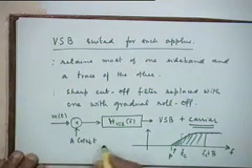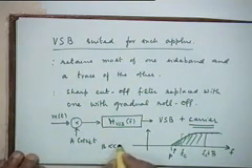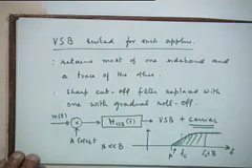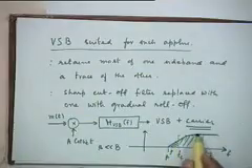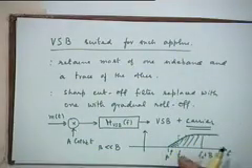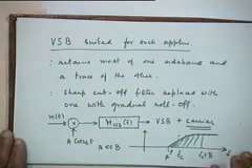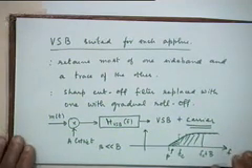Where beta will be typically much less than B. So you will still be saving a considerable amount of bandwidth, right, but you will be relaxing the requirements of your sideband filter. So your sideband filter design becomes easy, right?